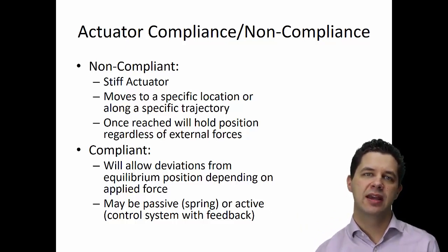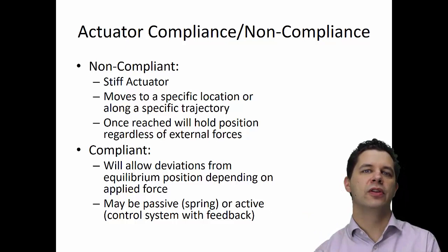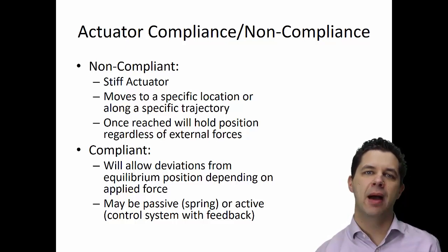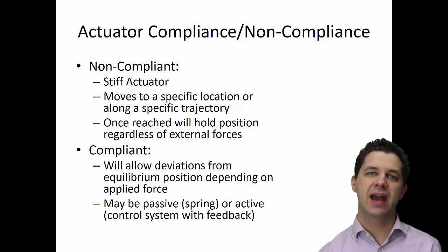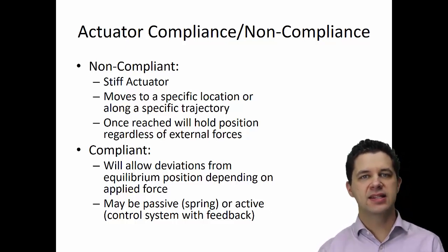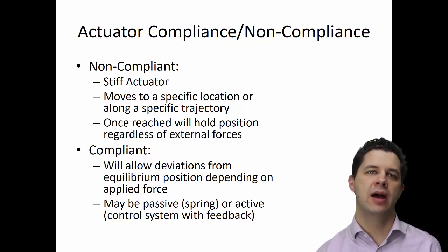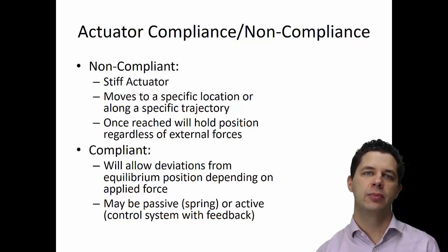Compliant actuators, in contrast to this, will allow deviations from that equilibrium position. So if we apply a little bit of force, it will move a little bit. If we apply more force, it will move even more. And this can take a number of different forms. It can be a passive system with a spring, or it can be an active control system that has feedback that senses the amount of force applied and allows more movement as more force is applied. And the idea is when we remove that force, it will move back to the equilibrium position that it was at previously.